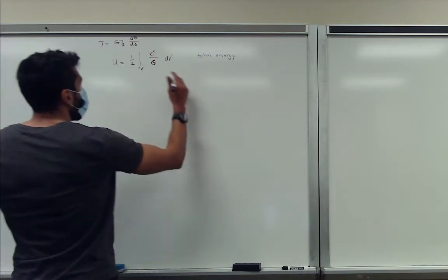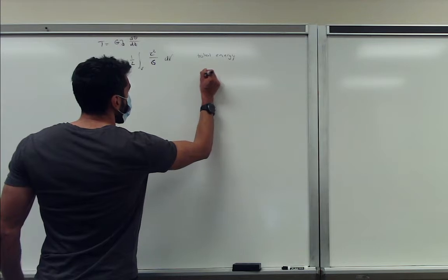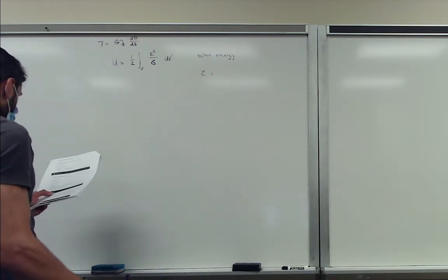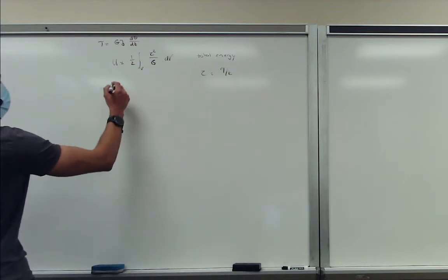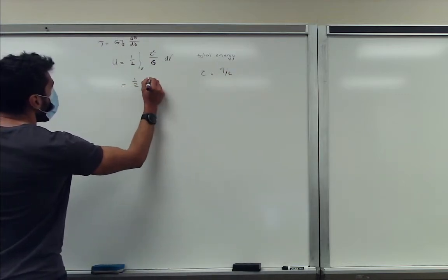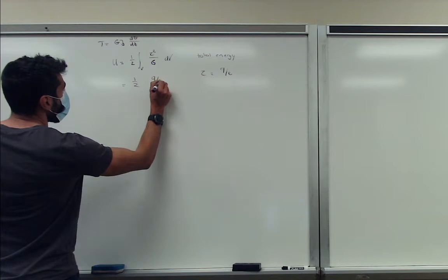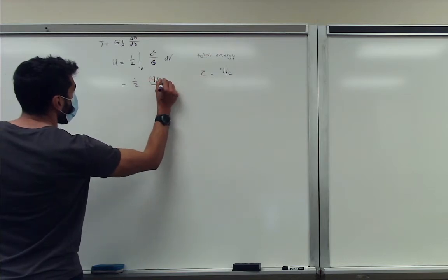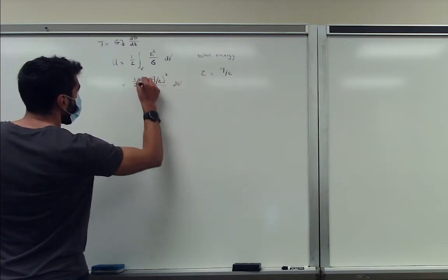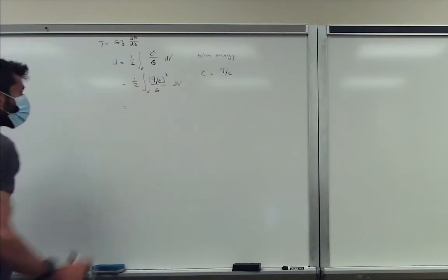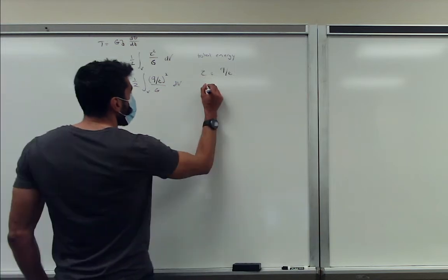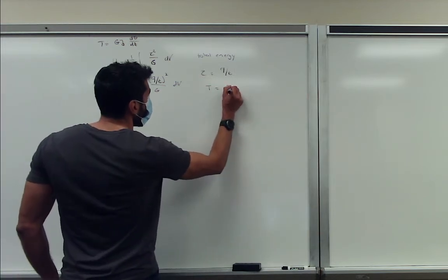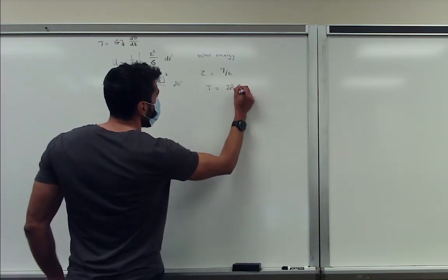So here we know that shear stress is equal to the shear flow divided by thickness, so we can substitute that back in. Then we get the integral over the volume. And we also know that in this case the torsion is equal to 2 times the enclosed area times q.